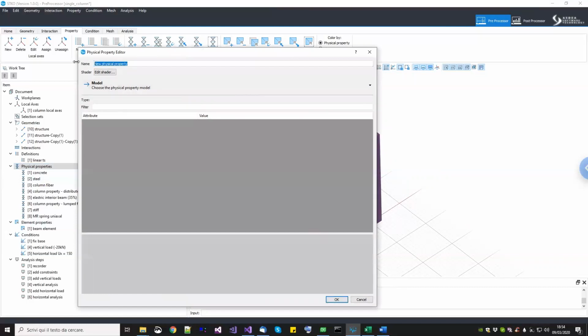Or actually before, for the zero length. So moment rotation, zero length. And another advantage of using the hinged beam in STKO is that STKO will automatically create the zero lengths and will assign the local orientation of the beams. Now in this case, they are globally aligned. But imagine if you want to create a hinged beam in a skew direction, STKO will do it for you. So it will be extremely easier.